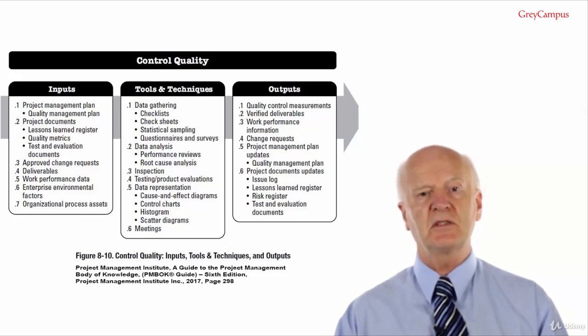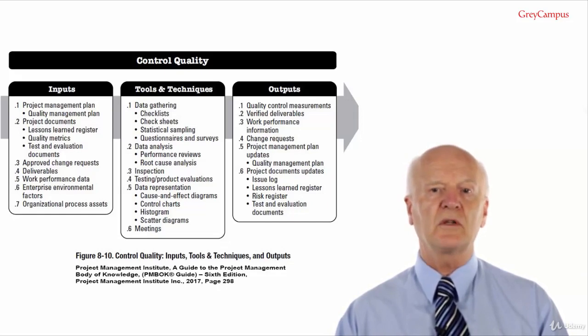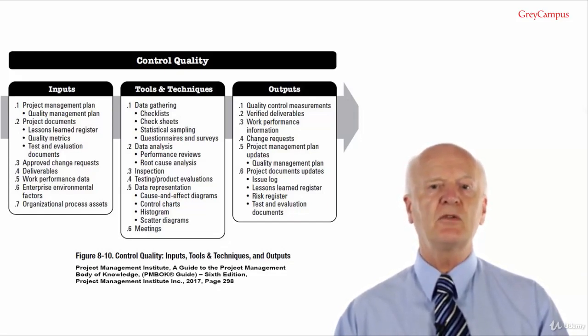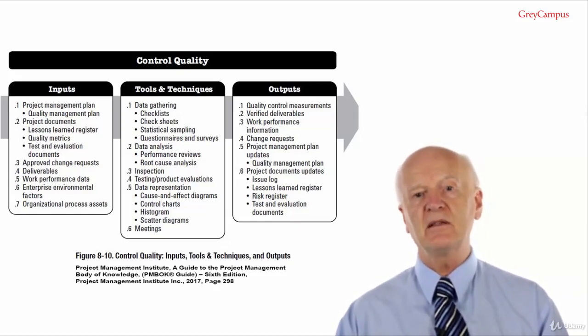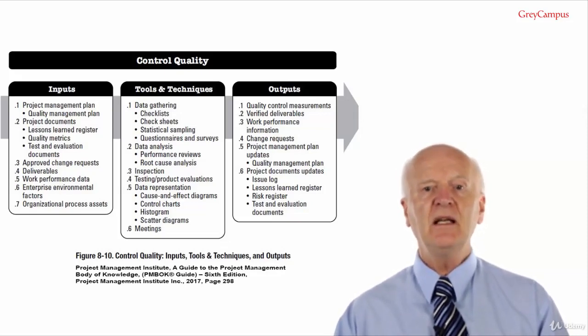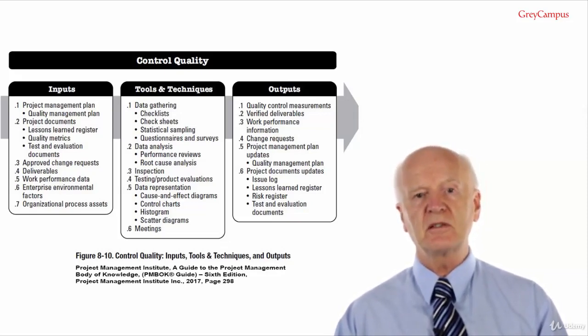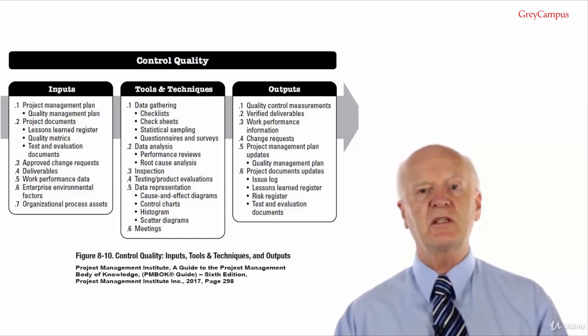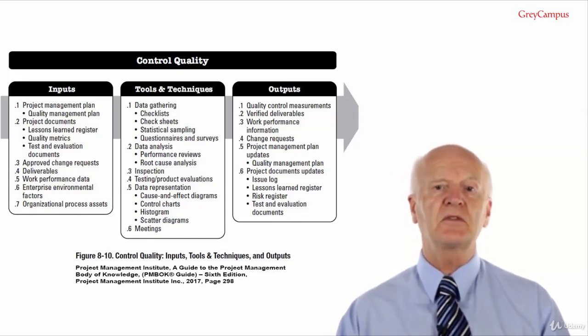6. Check the dashboard display against a picture of how it should look. Report any errors. 7. Rotate the ignition key clockwise 1/4 turn. The key should stop turning. The transmission not engaged warning light should display on the dashboard. The engine should not start. Release the key. It should return to its initial position. The transmission not engaged warning light on the dashboard should extinguish. Report any errors.